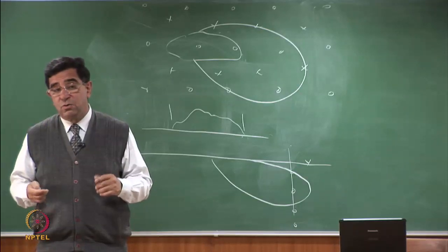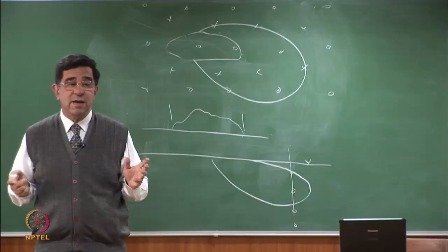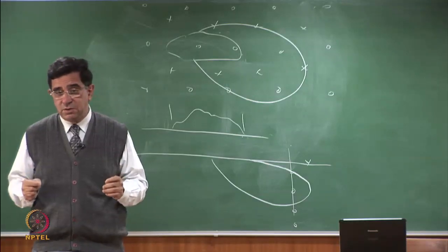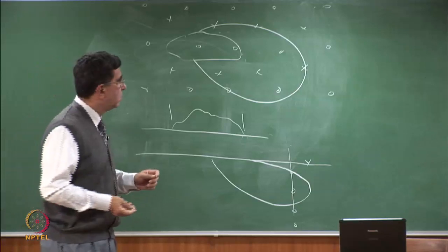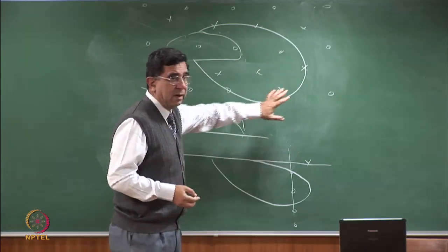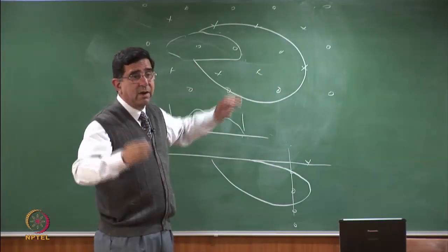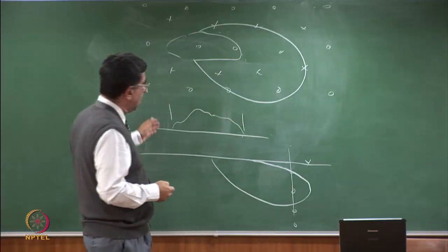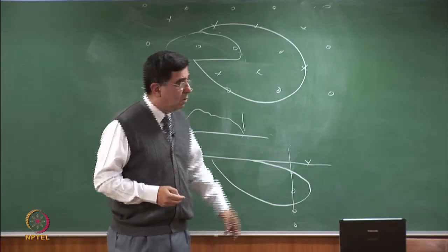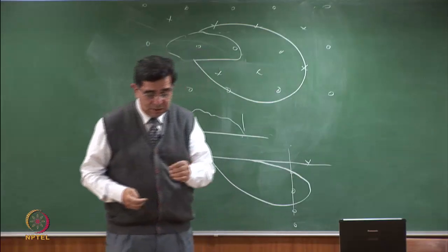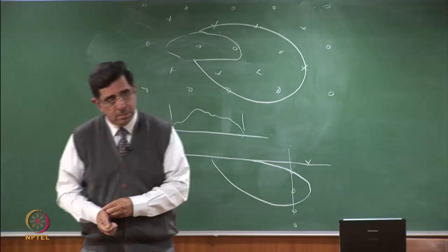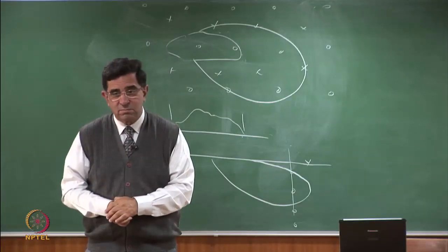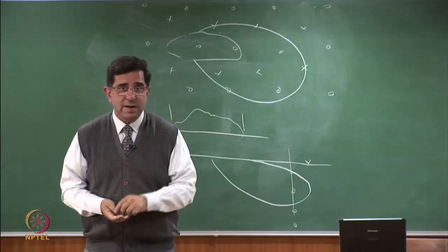Around old landfills, you'll first have to detect the extent of contamination. And we are still looking at subsurface contamination. So to detect, you should be able to do a lot of things in plan, first along a coarse grid, and then along a finer grid, and then you should be able to do something in section. At all these locations, you should be able to pick up discrete samples from different depths. I think so. If there's any other way of doing it, fine.